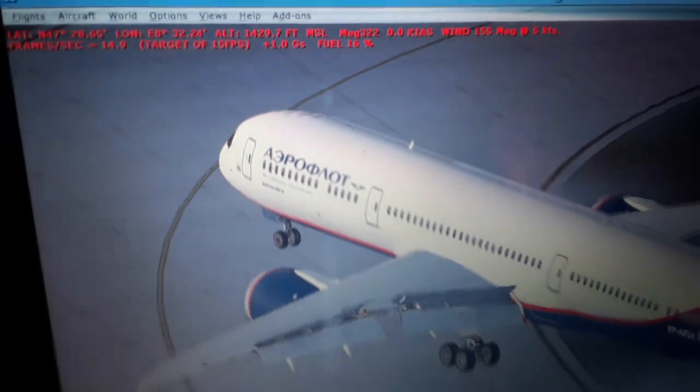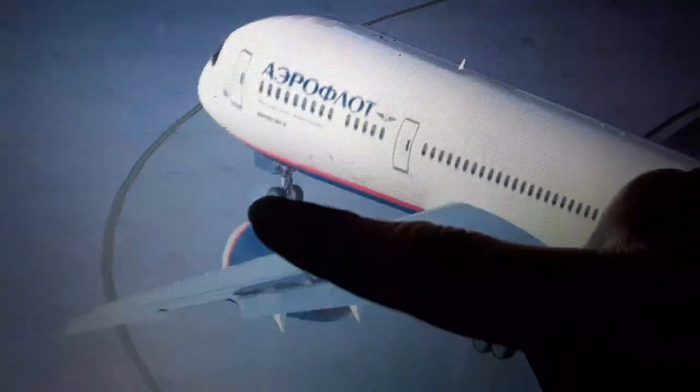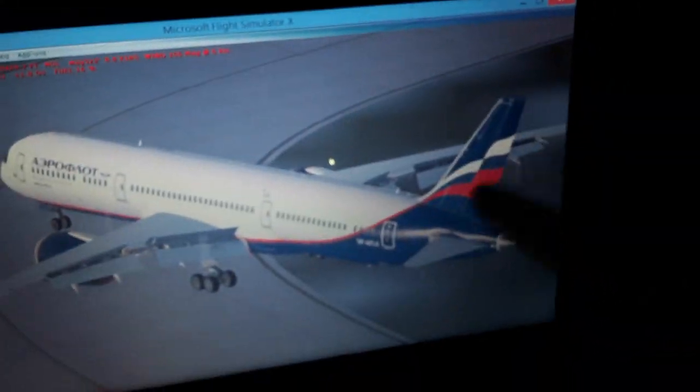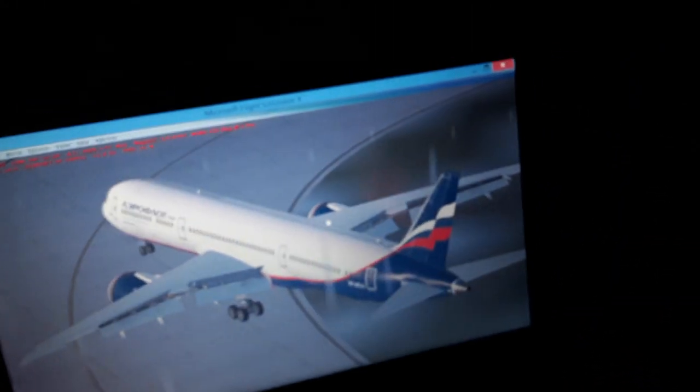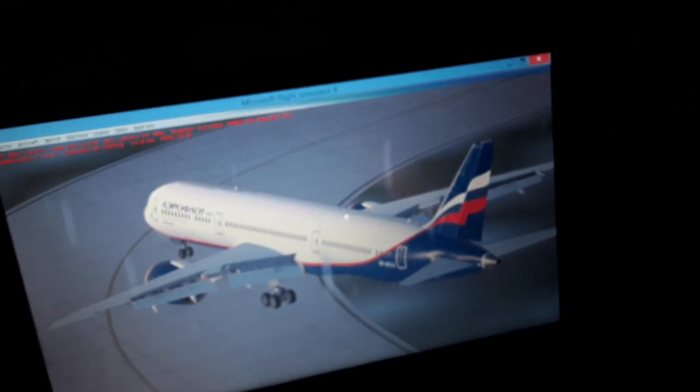Also we have the nose wheel steering. You can see the nose wheels over here. So we have also directional control on the ground, like 76 degrees left and right alongside with the rudder on the ground from an initial airspeed of 0 knots, like 45 knots. We have 76 degrees either left and right deflection using the rudder pedals over here, as you can see.